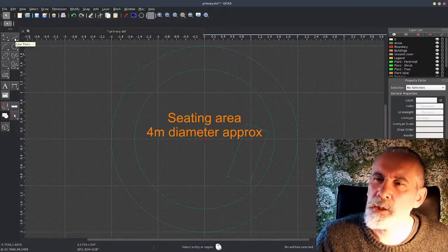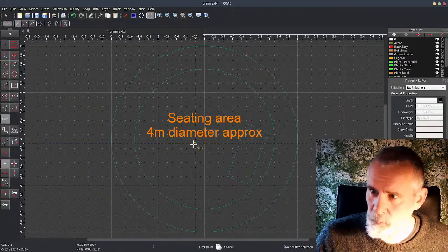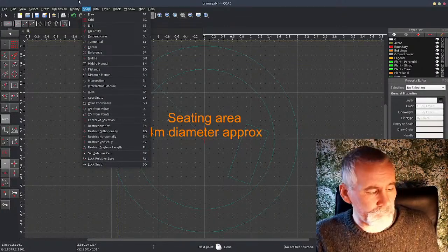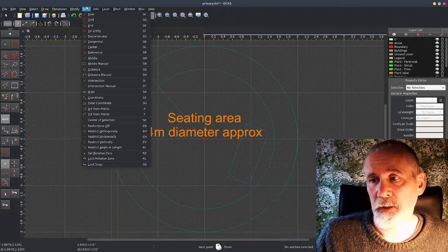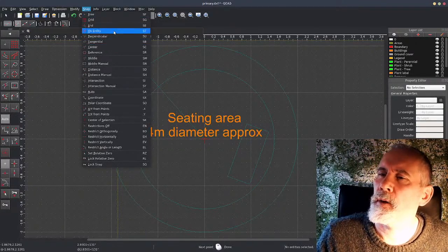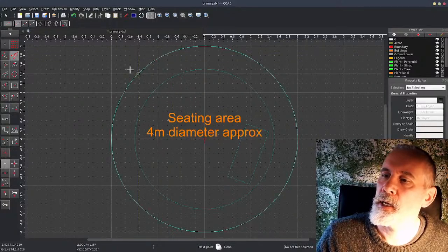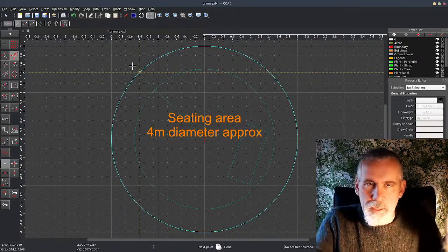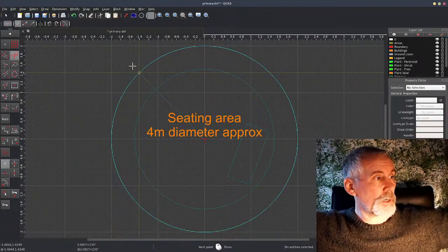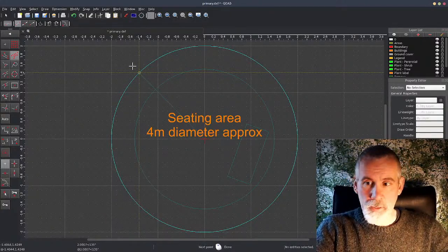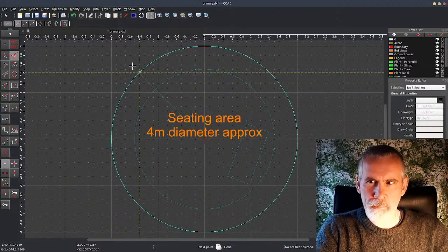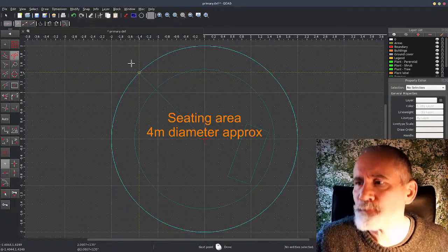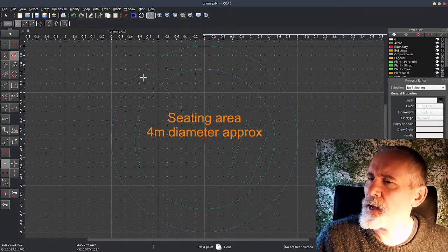So I'll get the line tool, point to point, and then I'm going to use the snap tool. It's really important to figure out how to use a snap, because I want to snap to the entity, on an actual object itself. You can see here it's snapped onto the circle itself. I want to leave that, imagine sitting down and you're surrounded by a low circular wall, and I want to leave that horseshoe shape. I want it fairly, not massively open. I still want a bit here and a bit here, but enough space for a couple of people to walk through. So I'm going to do it around about like that.